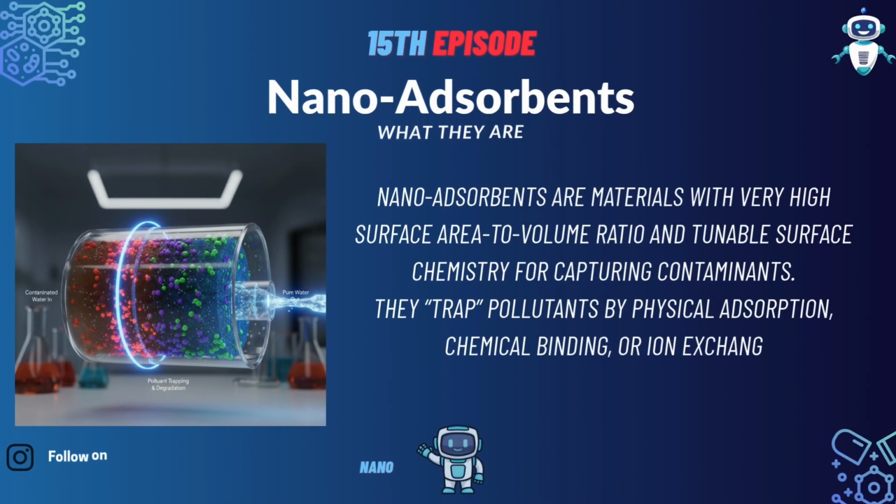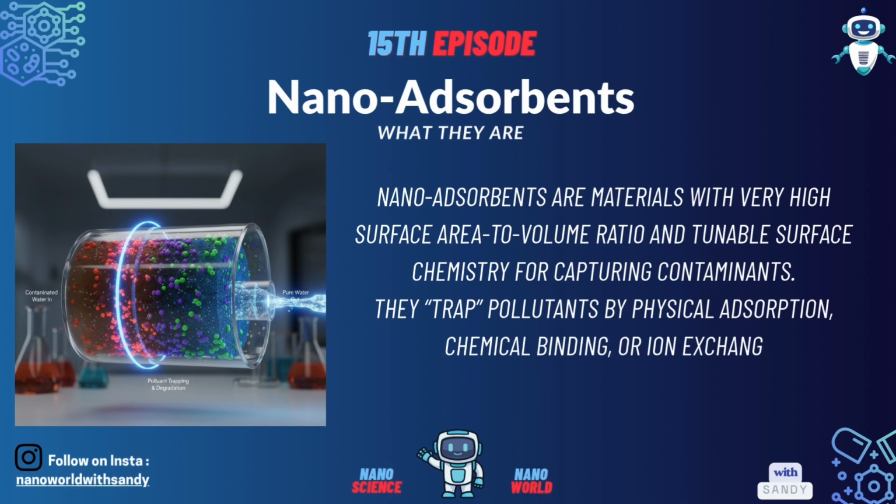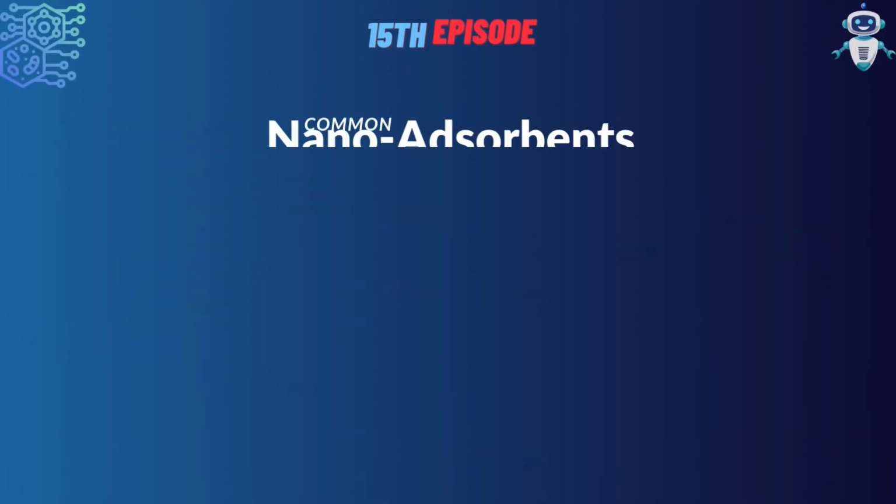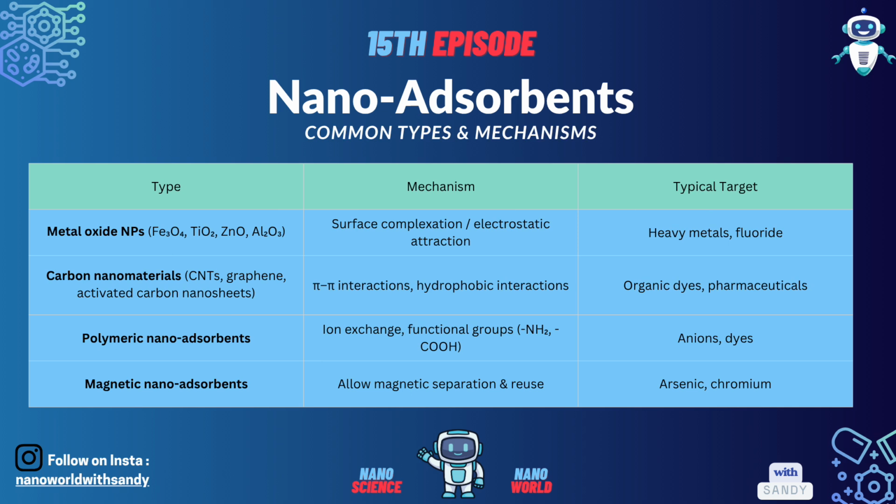Our second solution is nano-adsorbents. These materials are defined by their very high surface area to volume ratio. This tiny size means they have massive surface area, sometimes up to 1,000 square meters per gram, perfectly suited for trapping pollutants. They trap contaminants through physical adsorption, chemical binding, or ion exchange. This is a surface level attachment, like a sticky trap. Common types: think metal oxide nanoparticles for capturing heavy metals, and carbon nanomaterials like activated carbon for binding organic dyes and pharmaceuticals.